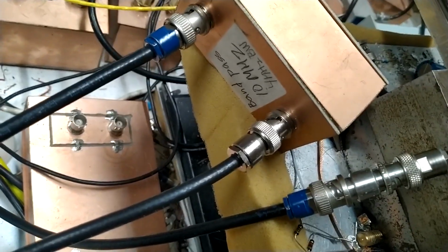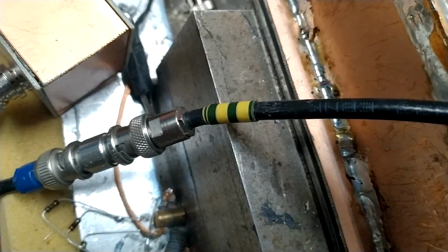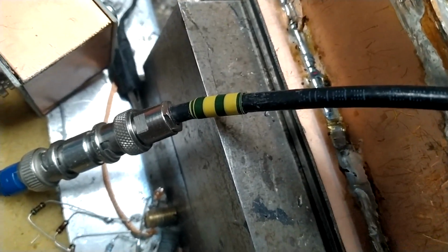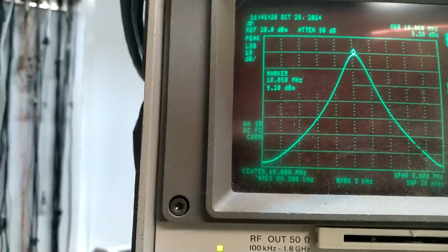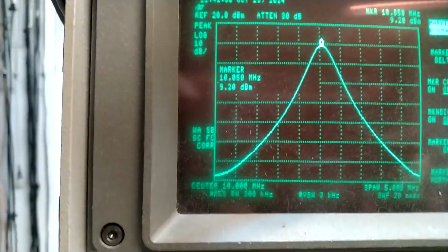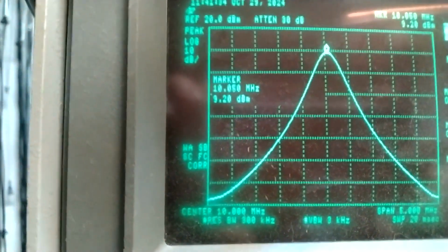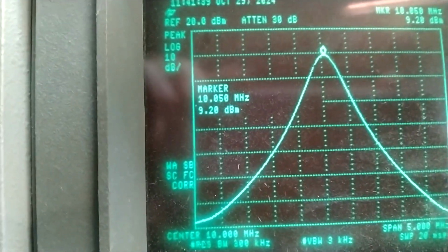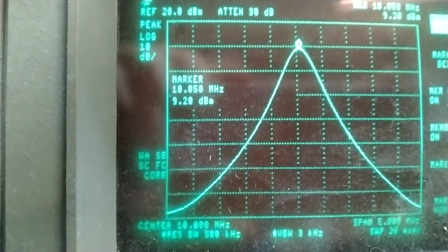Actually, when I take the same signal, moving it from the oscilloscope to the cable that I usually use to route signals up to the spectrum analyzer, here it comes. It is several meters long. So now I read 9.2, and the proper value would be 9.25, but the uncertainty is larger than the discrepancy. So I have a well-calibrated reading here now.